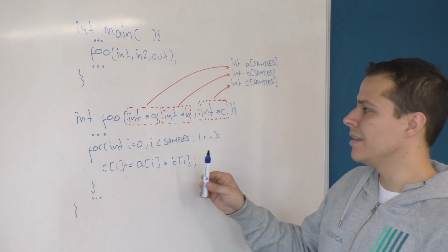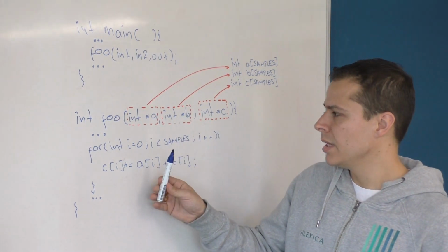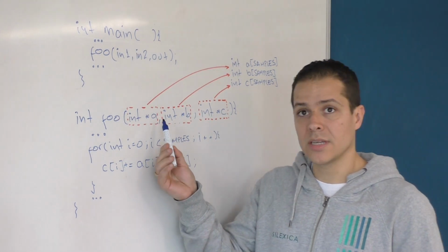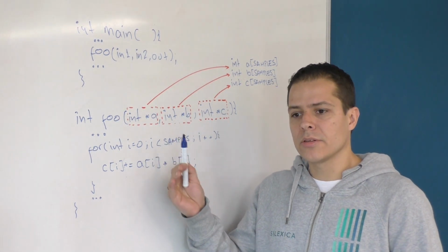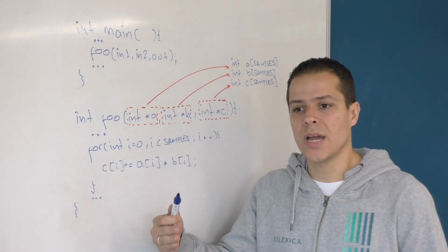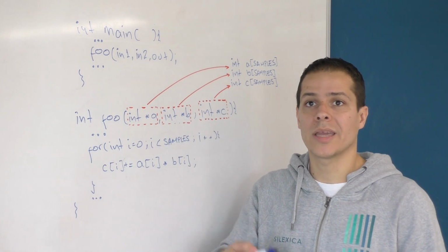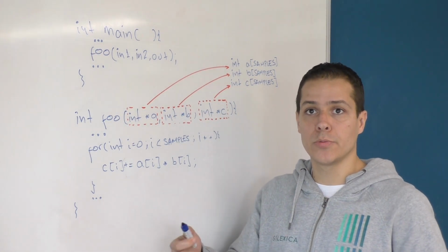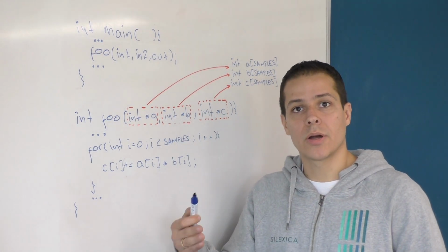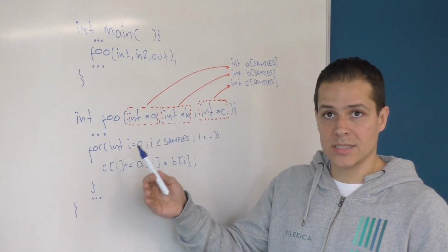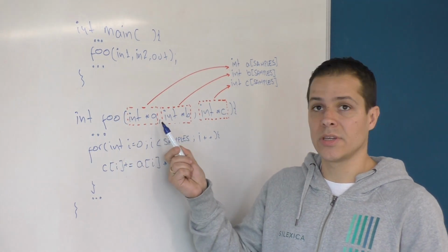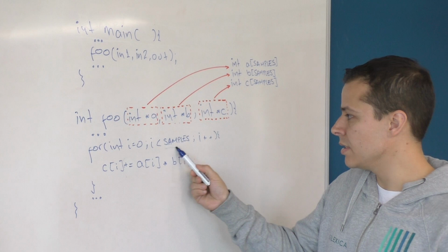I mean, the whole approach would be that you need to define the size of your arrays in order to have efficient hardware. So you cannot really say, okay, my A can be from 10 positions to 1,000 positions, because you will be wasting memory. So a good designer will go analyze the application and determine the size of the arrays, which in this simple case is samples.